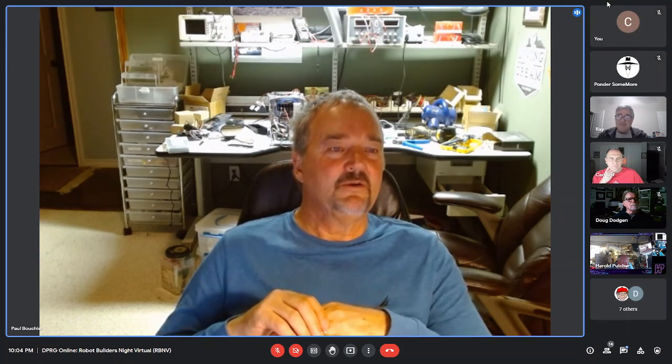Yeah, it definitely is, and you'd use load sharing, like one of those ideal diodes that I put in Mobot, would be a way to do that. In fact, I'm doing just that because my charger is downstream of the load of the diode, and so when it feeds the electronics, it can run the electronics indefinitely. But when I crank up the motors, that draws more power than the charger can supply. So the battery backs it up, and the BMS will turn on, connect the battery, and current starts flowing through. But it all needs to be pretty quick. There's no slow switching, or your voltage will droop.